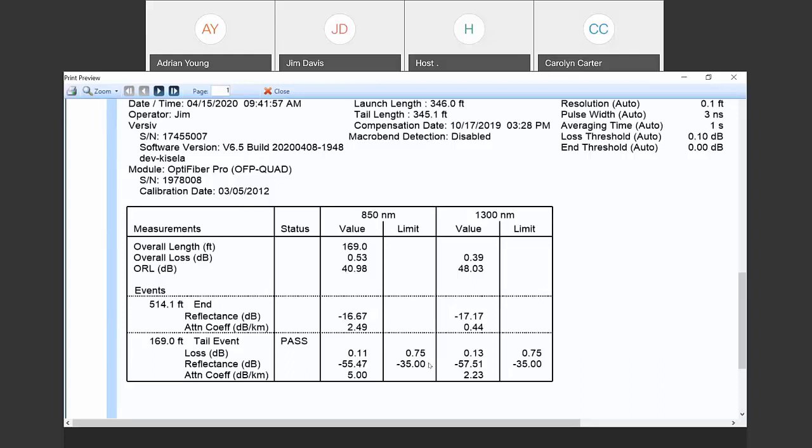And that is extremely common. When we start looking at traces, not in the enterprise, but outside plant traces, you can tell where different fibers have been spliced in, because you look at the trace and you get a slight up, and then you see the downward slope of the trace, and then it drops down again. So you can actually see it's extremely common. It's principally the reason why the vast majority of people shoot it in both directions and take the average.